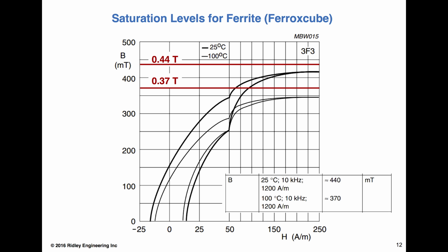They're trying to condense the curve here without going to a logarithmic curve. And I think this gets to the standards issue, that there's no mention that they've done that. I don't know if I've ever seen a linear axis before where the linear axis changes in the middle without somebody telling you, hey, we changed the scale, and that's why you've got the break at 50 amps per meter.